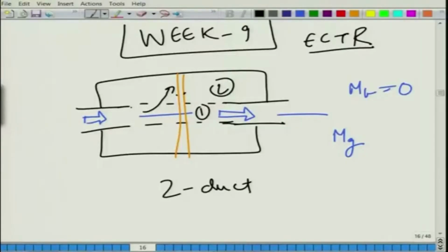So, this is like a discretized system, and another thing that I want to tell you is that we are assuming the grazing flow in a straight through duct to be constant throughout, but it will never be constant. As the flow passes, the grazing flow will tend to decrease, and a little bit of non-zero flow will be there across the perforated element, even in a straight through muffler, that is a 2 interacting duct muffler. Then it will be minimum somewhere in the middle, and then it will gradually pick up and reach a steady value. A CFD analysis would do proper justice.